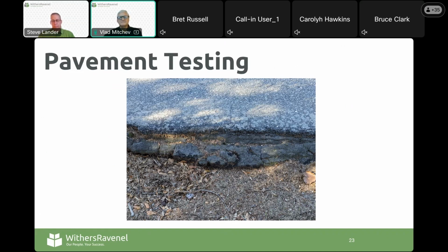However, in this case, you can see how the block cracking that you saw previously extends all the way to the bottom of the sand asphalt. And we also verified with the municipality and from our own observation that there's no aggregate base. So the pavement consists basically of 7 to 8 inches of asphalt, which is 2 inches of surface and 5 to 6 inches of sand asphalt. And the cracks go all the way through.